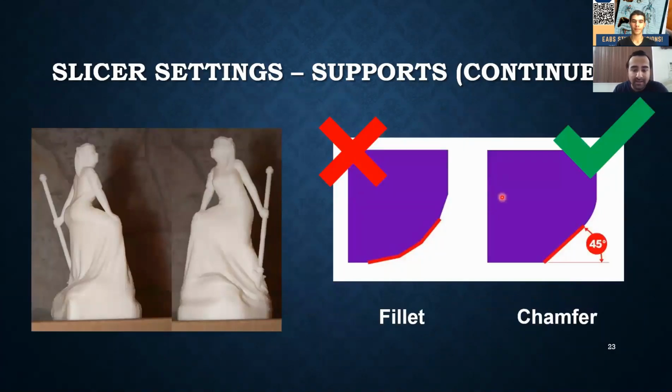So one way that you can get around doing this is over here, where you make your model. In this case, it's a little sculpture that has features in it that are their own supports. You can imagine there's this rod structure right here that is affixed to the bottom of this base, and the hand is grabbing it. So there's no part of this structure that is beyond 45 degrees. So this can print entirely on its own perfectly.